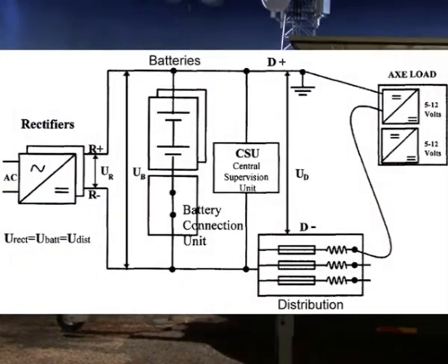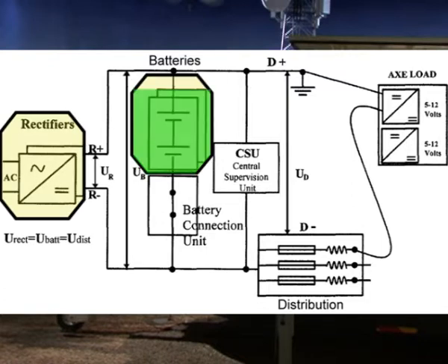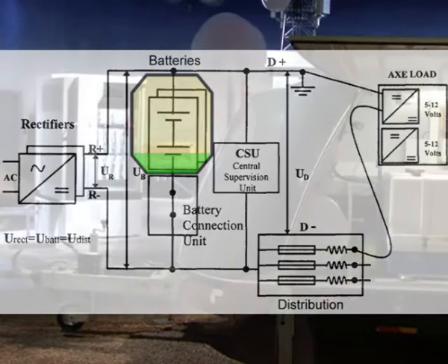In a full float system, the rectifiers are connected in parallel with the batteries and the telecommunication equipment, and a constant DC voltage is maintained to these units. In such a system, the rectifiers continuously feed the batteries so that they're kept fully charged during normal operation. In a mains failure, the rectifiers are no longer supplied with AC and thus can't rectify the AC into DC. So the telecommunication equipment will have to be powered by the batteries during mains failure. This DC feeding from the batteries starts automatically.